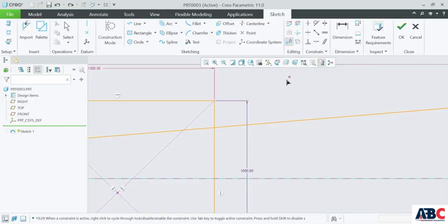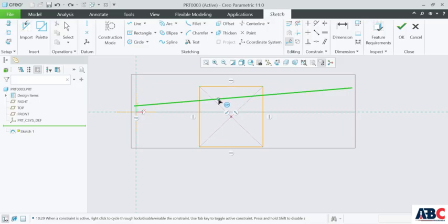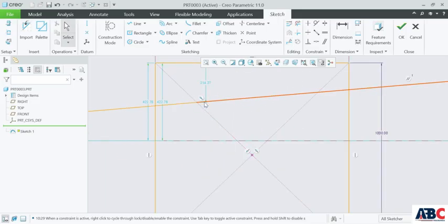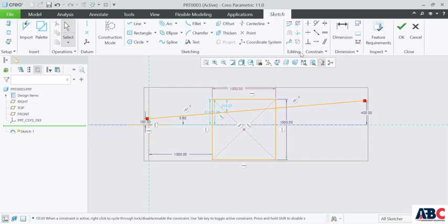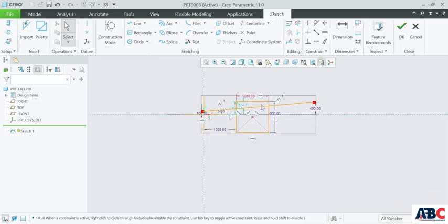Then there is a divide, so I will click on this line, I will click here. What it will do is divide the line at this point. Let me redo this process. I am selecting this line here, the complete line has been selected, so I will divide it at this point. Now I can select this separately and this one separately. So these are the editing options. We will be seeing another one. Simply delete this.